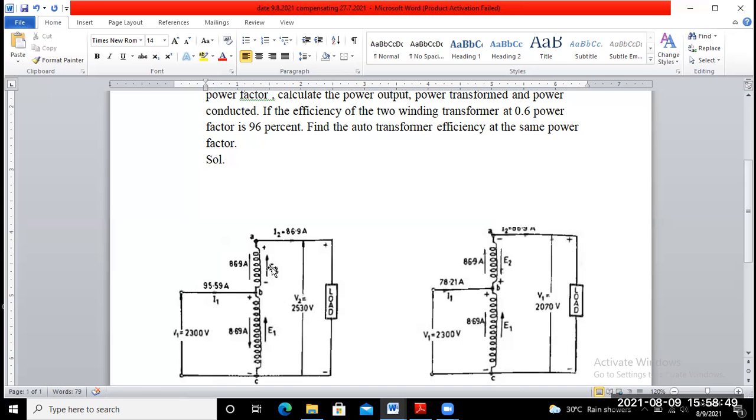In this way is the secondary side winding connection. Suppose you consider polarity with this one positive and this one negative, so this voltage is the summation of the two voltages, that means 2300 volt and 230 volt. If you take the reverse of this connection, that means the EMF E2 of the secondary coil has this one positive and this one negative.